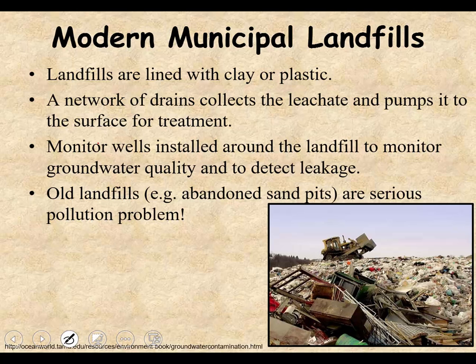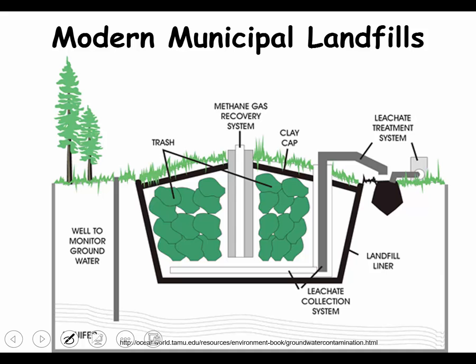So as they went away from that, the first thing they started doing is trying to find geologic areas where they're clay rich. So first of all, forget the sands and sandstones, focus on clays and claystones. Secondly, line the base of that particular landfill with something impermeable like plastic and clay, and then intercept any leachate that forms, because leachate always forms, by a series of drains, and you pump it to be processed. And then you, by the way, monitor to make sure that there isn't a leak. Okay. So it might look something like this.